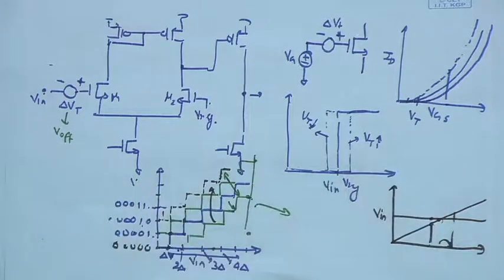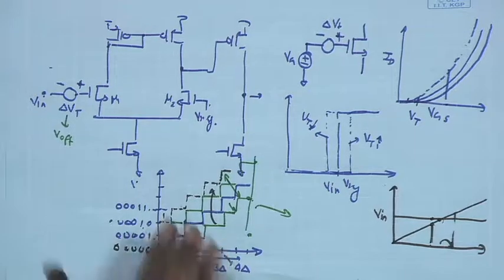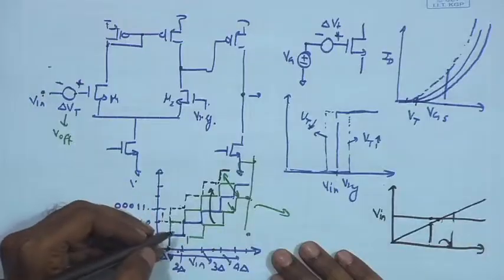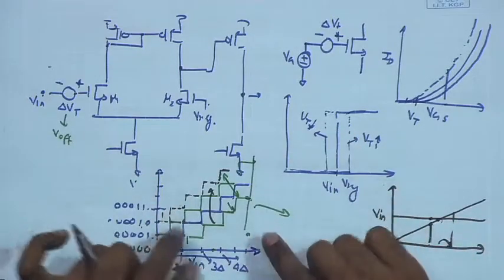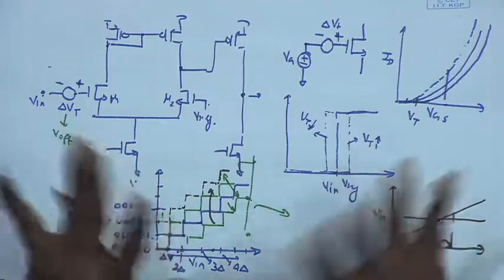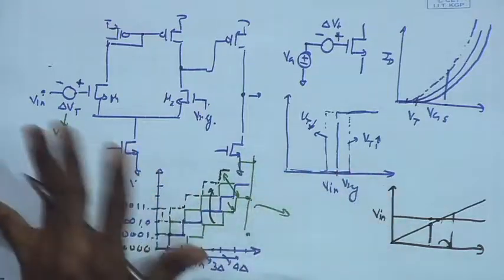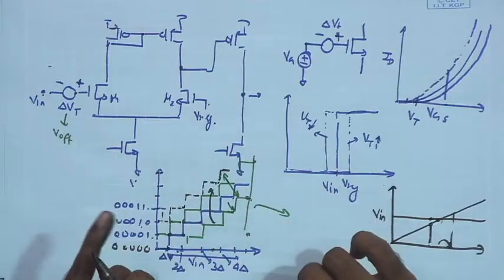In the example that we have taken, the constraints are relatively relaxed. We are assuming full swing 0 to VDD, and the delta V, or the resolution in voltage domain that we are trying to see, is around 15 millivolt. The offset values can be of that range, 15, 30 millivolt, you can go to that. If the precision requirements are higher, maybe 8 bit or 9 bit, there you can see that many more bits will get corrupted. So, here we have taken the resolution of 7 bit, and as a result the delta V, the analog resolution of the comparator, is 15 millivolt, and the offset that you can get in 180 nanometer can be of that order, meaning a few tens of millivolt.